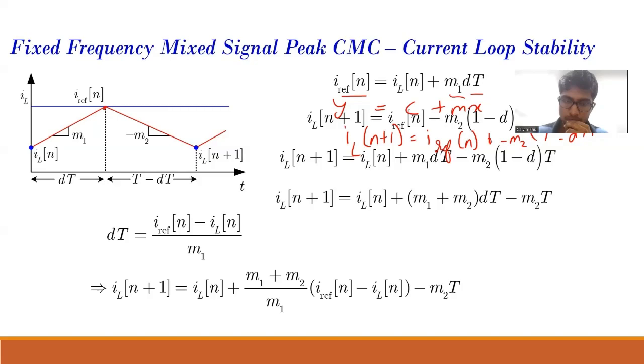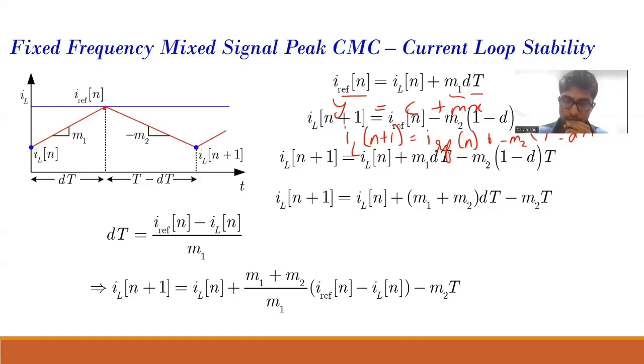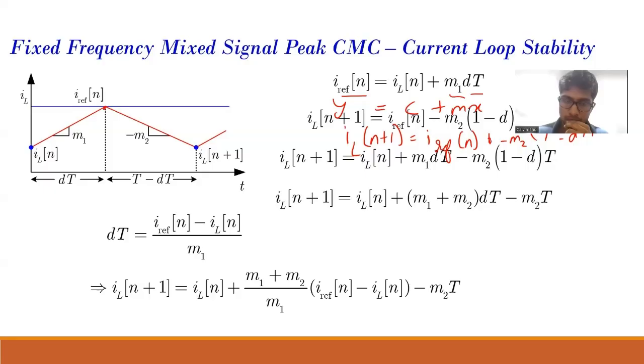what happens? When I give the set pulse over here, there will be certain spikes. Suppose by chance that spike is so large that it will make reset high and turn off the switch. So the switch has turned on very quickly and then turns off. That is how it would happen because of the spike.